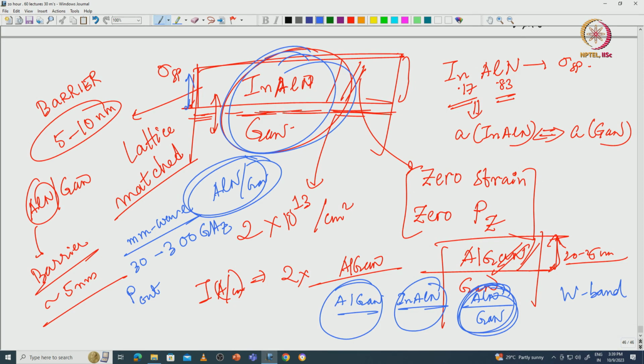But it is highly speculated that AlN GaN and indium aluminum nitride GaN HEMTs are most likely going to be used in such highly scaled technologies, and in such highly scaled devices, even nitrogen polar devices, about which we are not going to talk much in this course. Nitrogen polar devices are also very promising for reasons that we will again discuss, but in general, for all typical RF frequencies, S band, L band, C band, X band, a few gigahertz to a few tens of gigahertz, typically AlGaN-GaN is the wafer, material and device of choice which is available commercially.